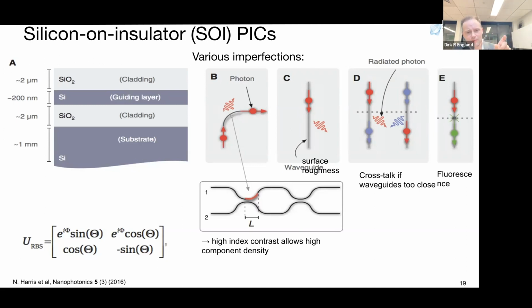Or if you do have a large enough waveguide that is multimode, you try to stay in the fundamental mode by an adiabatic turn, so that you remain in the fundamental mode. That means a very slow turn. Or in this case, you want to have a slow convergence of these two waveguides in this directional coupler, because if these modes came together too quickly, then you would not stay in the adiabatic limit, and you might excite some higher order modes of this two mode coupling structure.